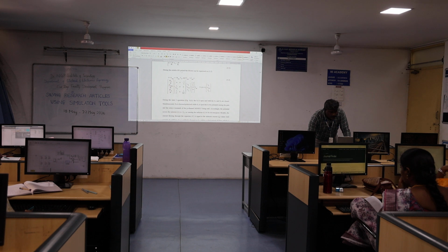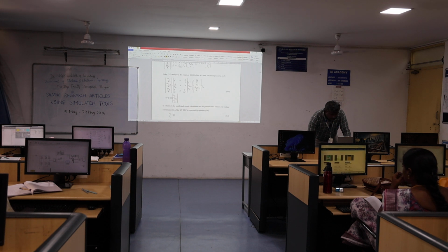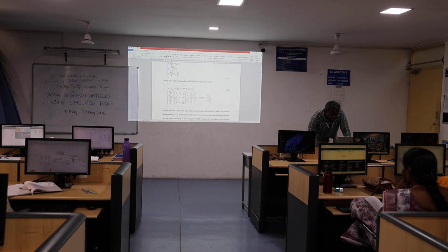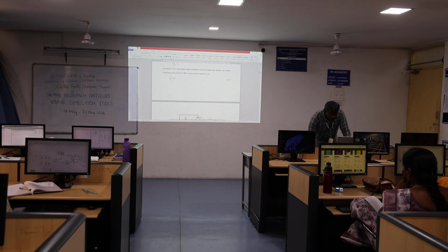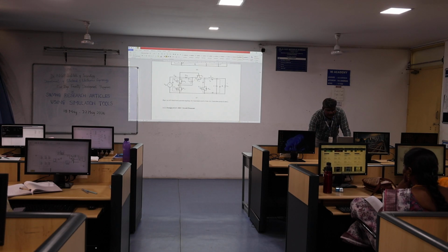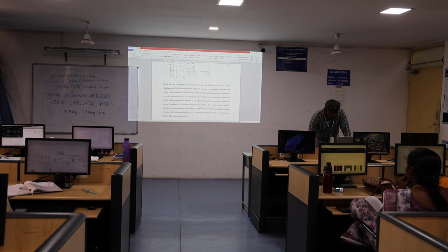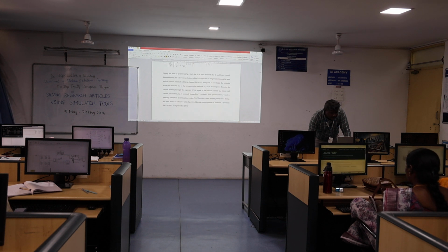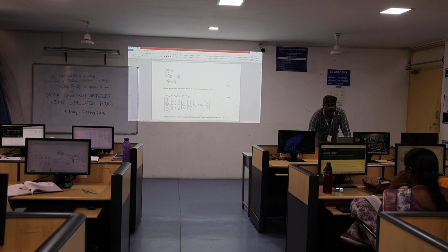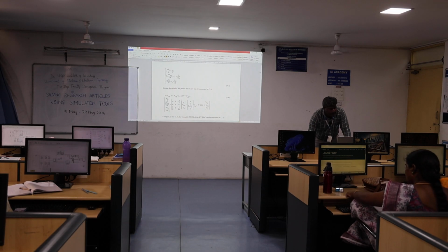Next, during the switch off time period. Again we move on to the equivalent circuit. Now during the switch off time period, just see here, the voltage across the inductor: this is plus, this is minus. So one end of the inductor is minus and the other end is plus. Therefore the voltage across the inductor is minus V0. So now you can form the equation. During the off time, the voltage across the inductor, L into diL by dt, is equal to minus V0.